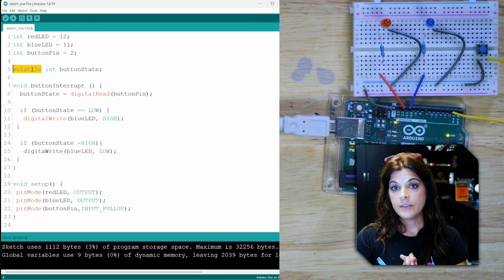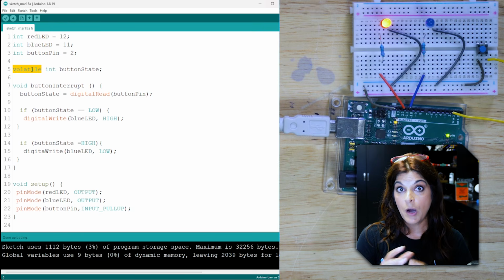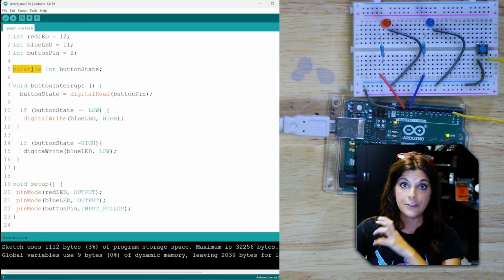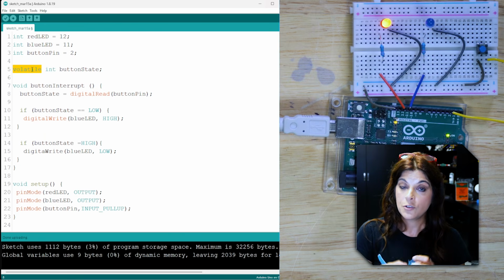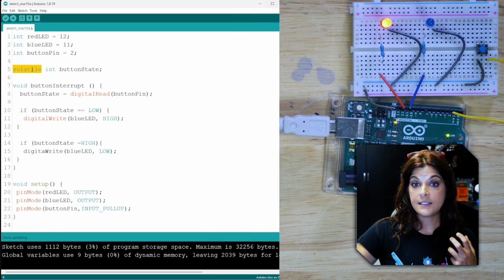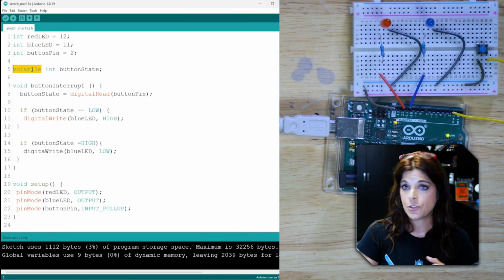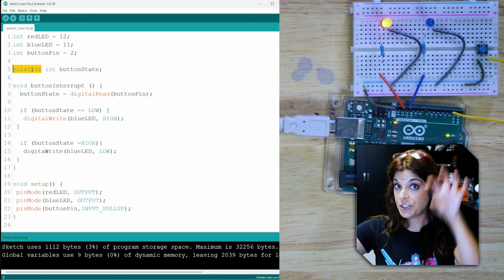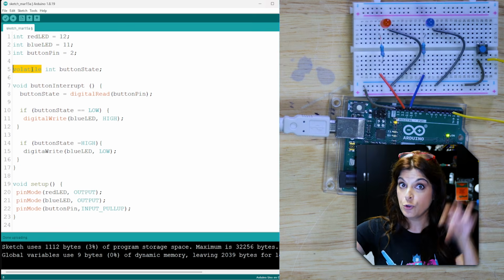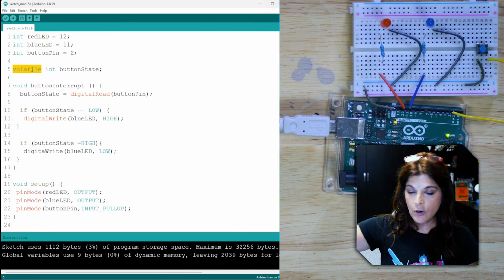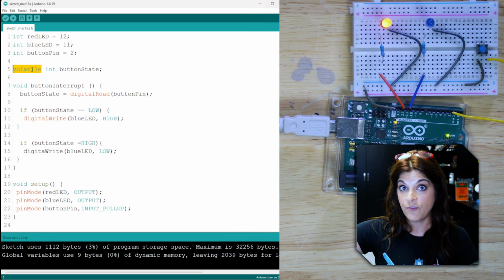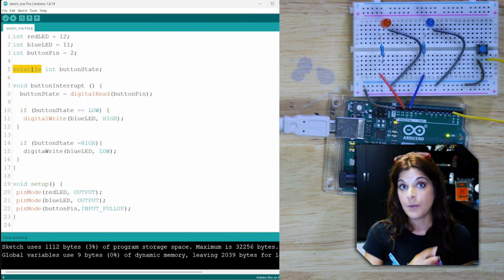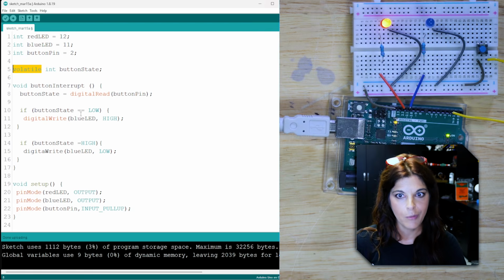This prevents the Arduino compiler from optimizing it and putting it in the storage register, like with all your other variables. It actually puts it in SRAM so it can be updated. So for instance, say that this is a variable that changes all the time, like sensor readings, button pushes. By the time you interrupt, that variable could have changed. If it appears elsewhere in your loop and that variable could change, well, your interrupt service routine could be running on the old value of the variable. So it's important to use the keyword volatile anytime you're using hardware interrupts with a variable inside.